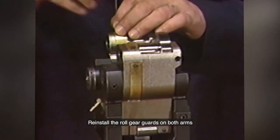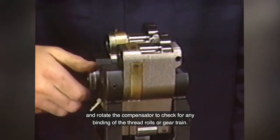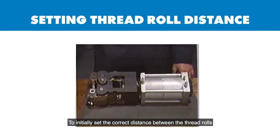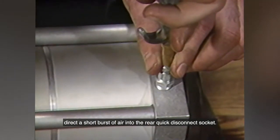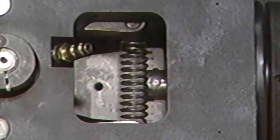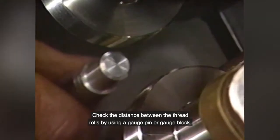Reinstall the roll gear guards on both arms and rotate the compensator to check for any binding of the thread rolls or gear train. To initially set the correct distance between the thread rolls, direct a short burst of air into the rear quick disconnect socket. This will move the wedge to the full forward position. Check the distance between the thread rolls by using a gauge pin or gauge block.